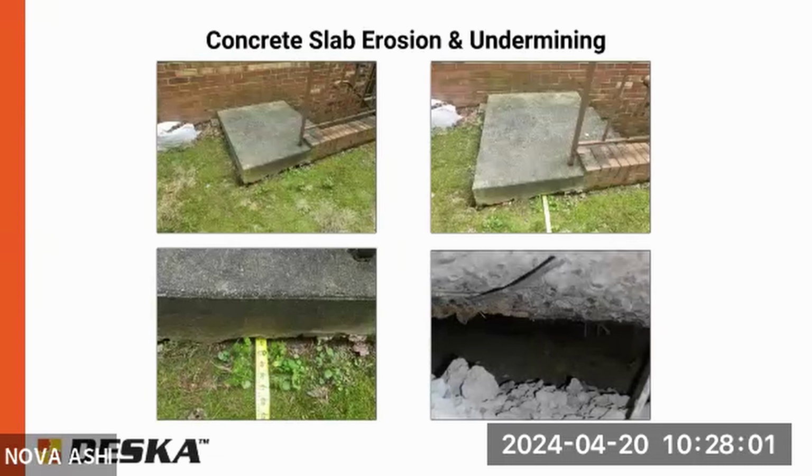You'll probably see this around a lot of areas, especially with drainage issues: voids below slabs. We were out here, the slab looked a little funny, had kind of a shadow around it. We got down and looked underneath, put a measuring tape in there, and it goes under 4 feet. So, a large void below the slab. It's not structural, but it's not going to get better. At some point, it's going to crack.